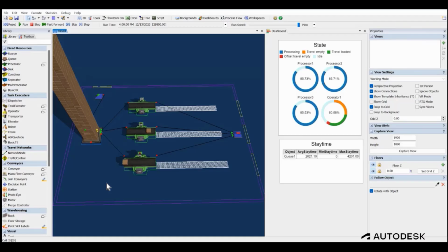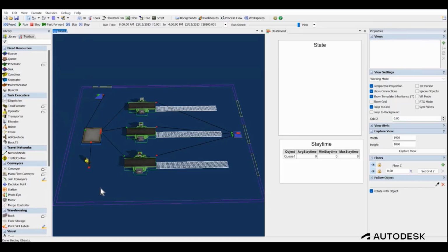Moving the queue closer to the processor could provide another incremental increase in production, but there is no way to eliminate much of the travel needed to service all three machines. Adding material handling is a viable option if the volume of boxes can justify the cost of the hardware, programming, and maintenance of the conveyor system. Kanban and batch flow are common techniques that are low cost and effective, and they would pair nicely with an automation solution. For example, using batch flow to feed an automated feeder on the processor could be an effective approach. Because of the cost, it's decided to try a combination of batch flow and automation to solve the problem.